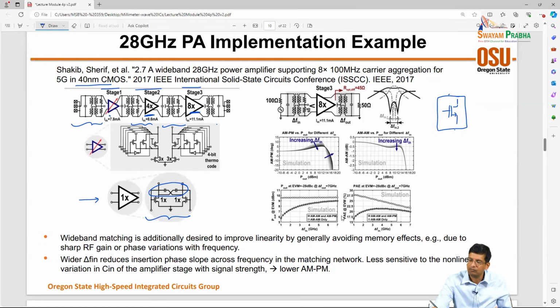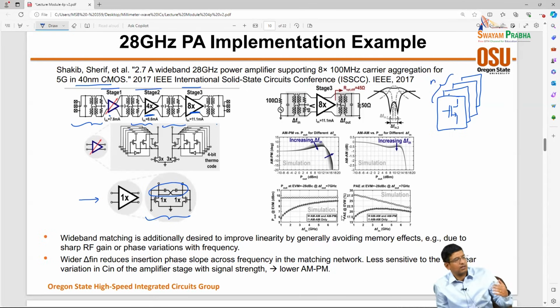And then we do load pulls with different number of these transistors in parallel, right. And that gives us an optimum load, and an optimum power, and we can decide, okay, we need n such parallel transistors. Now, of course, we have not considered all that would take to wire these transistors together.